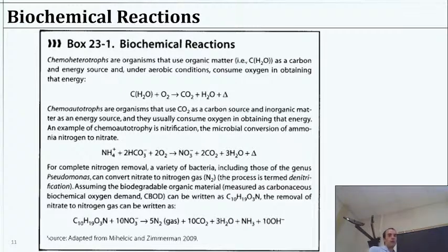So there's a few biochemical reactions that are identified as particularly helpful or common for artificial wetlands. So we would have chemoautotrophs here. We're going to take some organic carbon and oxygen, create CO2 and water, and some other stuff. So that's our typical respiration process. That's going to be all these bacteria in the soil, possibly also that would describe the plant matter taking stuff up.